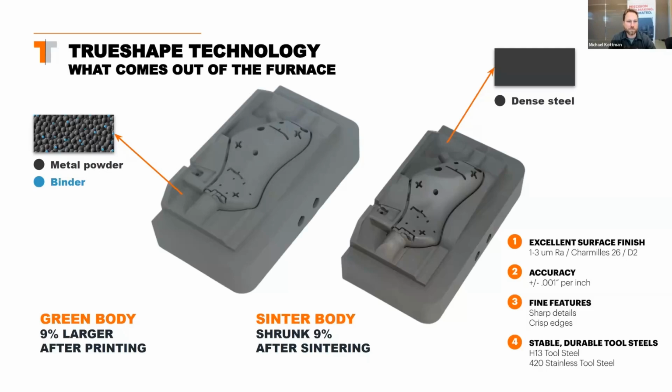medical. Awesome. And to explain that accuracy, the reason it scales with size, that's due to the sintering step, right? Because we can machine a green body to machining tolerances, but how closely we can predict that shrinkage is why it scales per inch, correct? Yeah, that's correct. On the machining side, we get the accuracy you expect out of a CNC on that green body. And then it scales with size because sintering does depend on how thick your part is and how easy or difficult it is for voids to migrate to a surface.